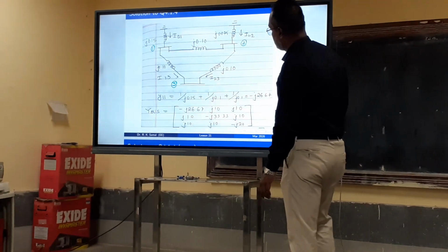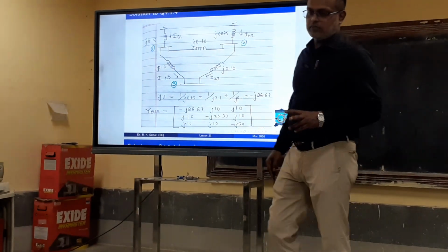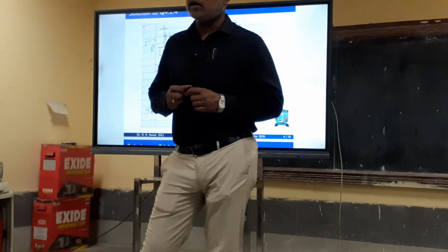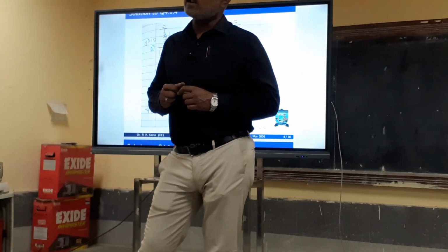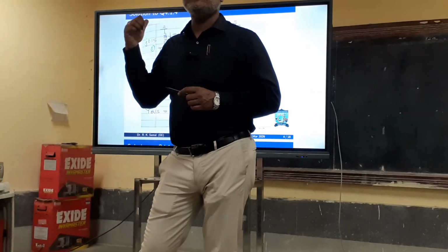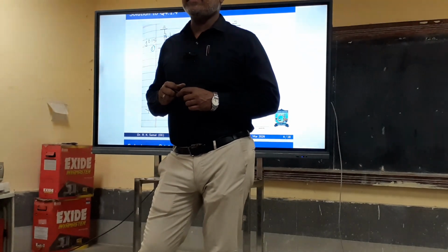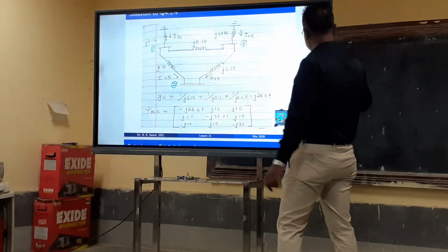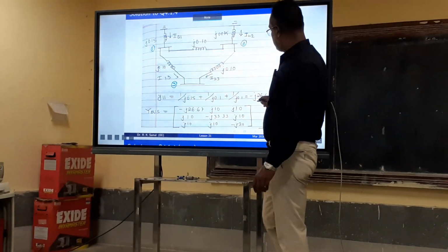So here, see what we discussed. We need Z bus for computation of the fault current. But Z bus, that is one algorithm in which we are going to develop Z bus. In this case, we will do that by matrix inversion. So we are forming the Y bus first.